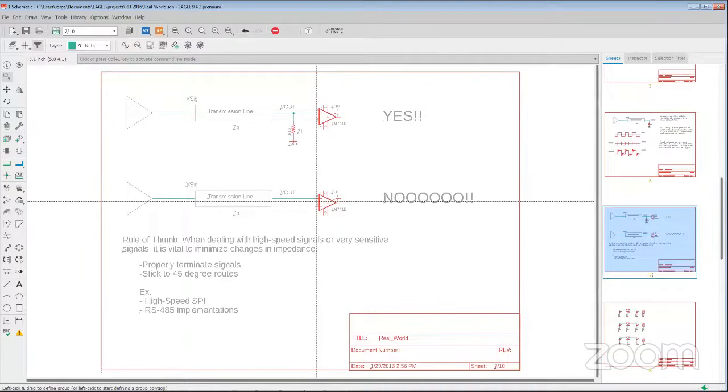So you have a transmission line. Typically, transmission lines are designed for the application to have a certain characteristic impedance. The most common is 50 ohms. You'll see 75. In some applications, 300 is also a standard. But definitely 50 or 300 going into a million or 2 million or more, that's a very big change in impedance. And that's going to create a lot of distortion in your signal. And that's what we're going to see here in the next slide.